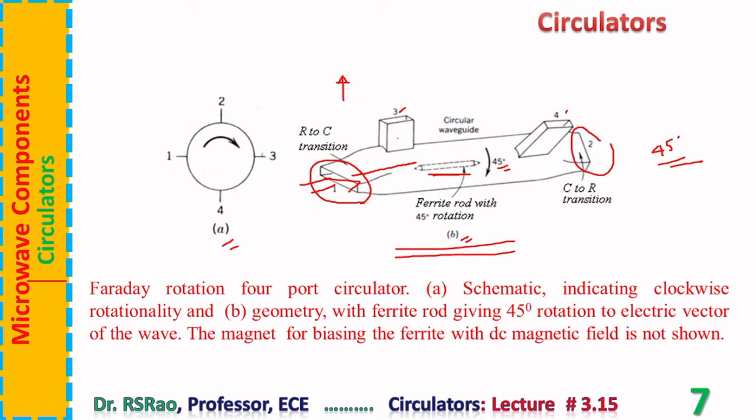The reason is this arm is not compatible with the structure of the wave. So it can in no way influence wave propagation. Notice in the arm with port 3, walls are vertical, and the field is also vertical. Then how can the field be sustained in this structure? For the field to exist, there should be two walls, two plates to originate the field and to terminate the field. But we don't have any horizontal walls in this arm.